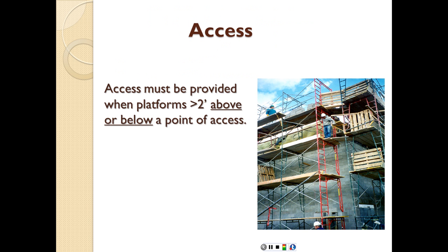How are we going to access these scaffolds? This one looks like a good scaffold. It's wide enough. It has the ladder-like access tool. It's properly braced. It's fully planked on the working surfaces, with solid wood, not plywood. And in this case, it has something that looks like a guardrail and mid-rail here. So this looks like a good scaffold.